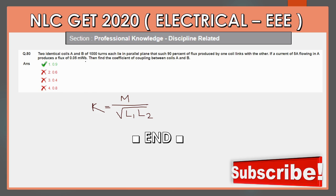So final question, it is asking two coils are given A and B, 1000 turns each, and they are placed in parallel planes such that 90% of flux produced by one coil links the other. So it is asking the value of K. We know that K value is nothing but M by root of L1 into L2. So if we apply the formula here, we can find out K equal to 0.9.